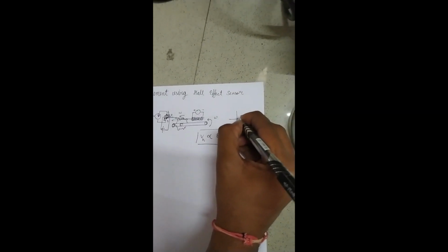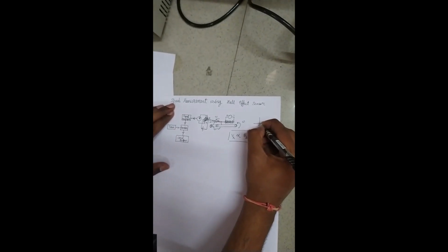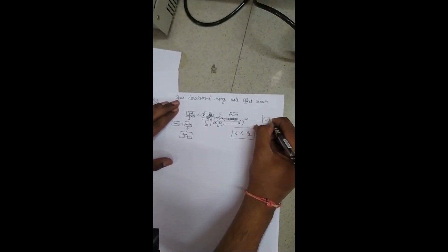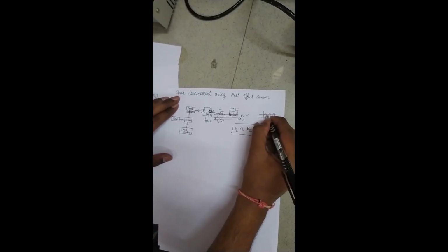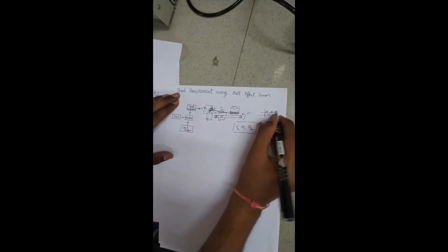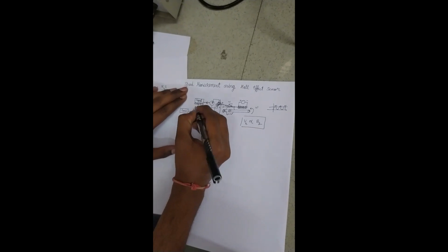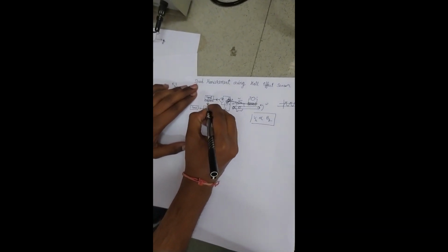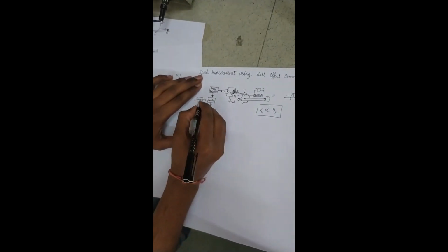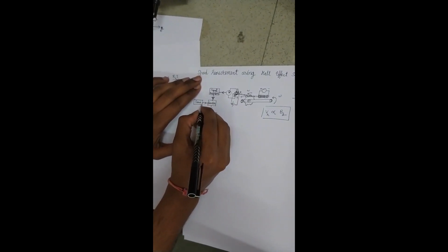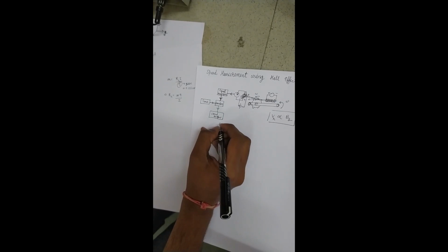Let's say the Hall voltage varies like this. So by setting a cutoff voltage and measuring the number of peaks after amplifying the signal, which feeds the data to the counter, using the counter we can count these peaks, and coupling the data with the timer, we can obtain the speed output. So that's how basically we can use a Hall effect sensor to measure the speed.